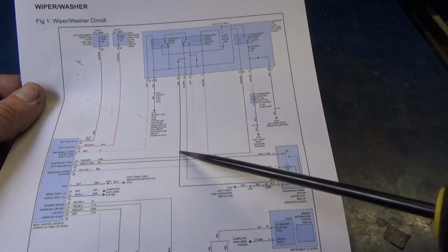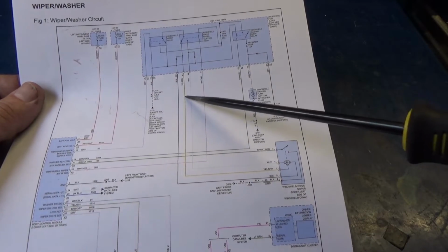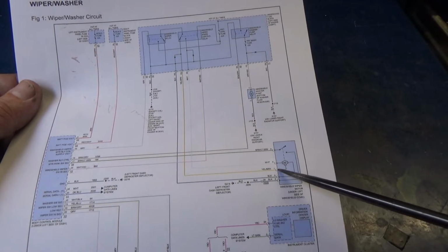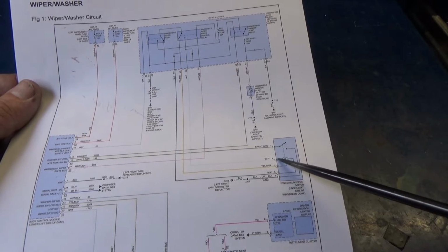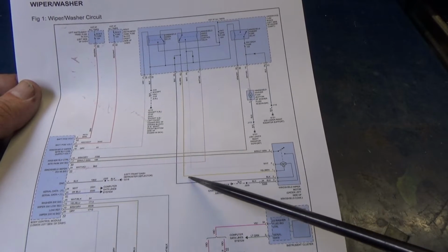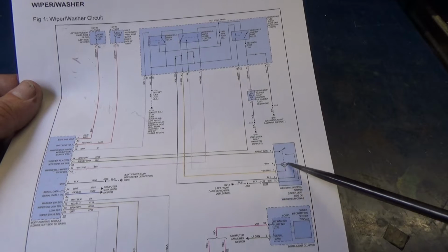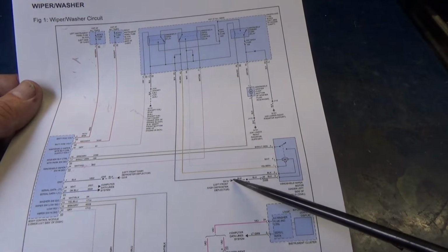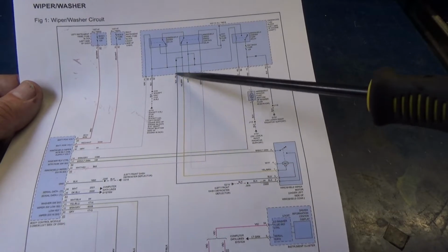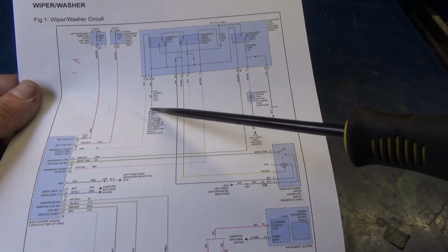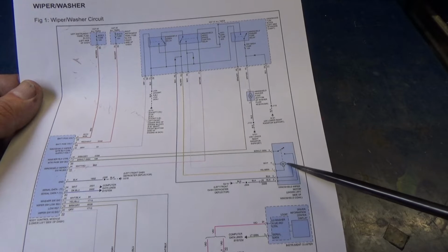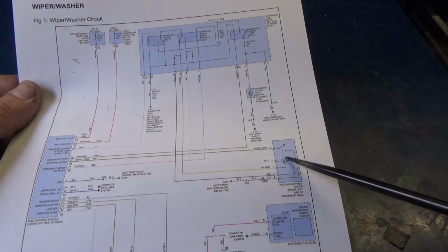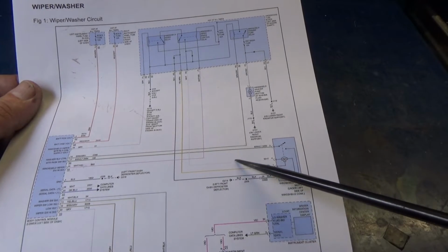Forget this circuit. Pay attention to this yellow wire. It's going to shoot power down here to the yellow wire, go right here to the motor, and turn it on low speed. So yellow is our low speed. Now, if you look right here on the motor, we got a ground. Actually, it's this black wire right here that goes up, and it goes down to this same ground right here. So this wire right here is the ground. The yellow wire is the low speed, which means that the white wire must be the high speed.